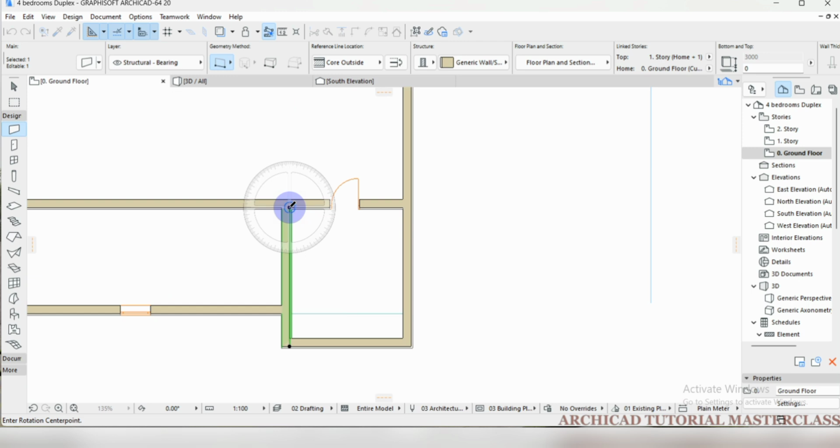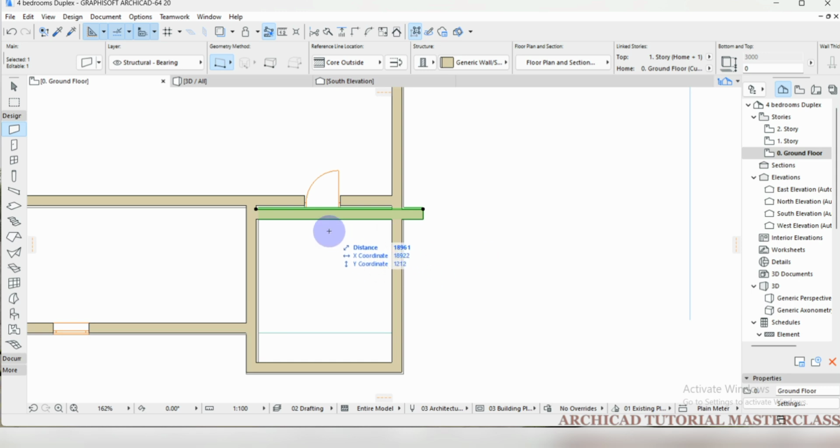So if you want to rotate a copy and you have already done this and you forgot that you're supposed to select rotate the copy, you just press your Control. You see, it will rotate a copy of it. Same thing applies to dragging. So you see, I'm dragging this way. So always make sure that you note your angle. So I can press my enter. You see, or you click or you press your enter. See, I've rotated the copy, so I can drag this.